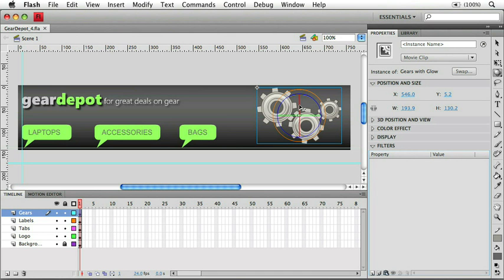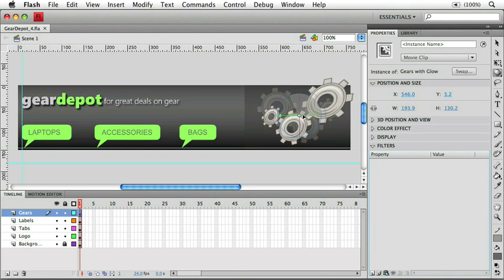And let's start by taking a look at the green handle running horizontally from left to right. If you move your pointer over this, you'll see a little Y appears below your pointer. This lets us know that this handle, when clicked and dragged, will actually rotate our graphic around the Y-axis. Click and hold down your mouse button on this, and go ahead and move either left to right or up and down. If you move left to right, you'll see it actually spins your graphic as if it's fixed to that bar in the center. So already this adds a pretty cool level of depth. Let's go ahead and pull this just a little bit so it looks like we've spun our gears maybe about 45 degrees to the right along this bar.